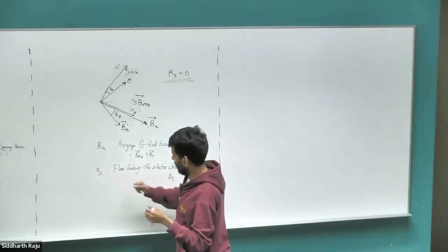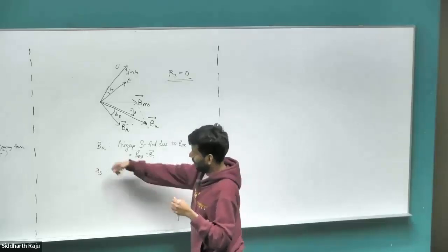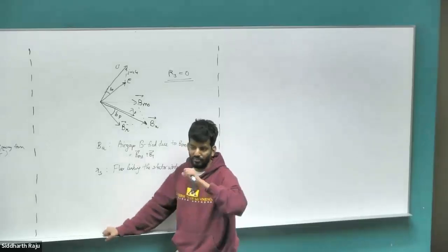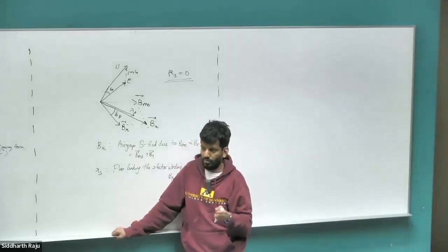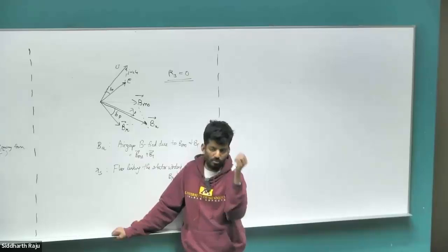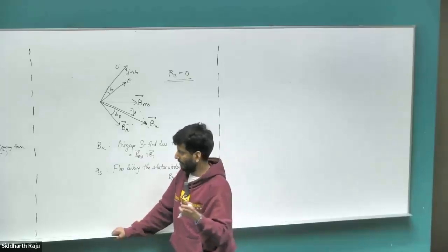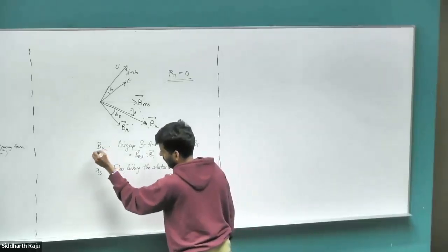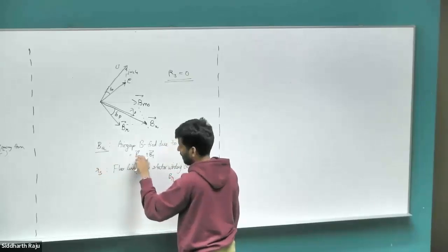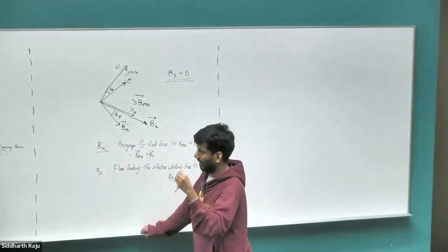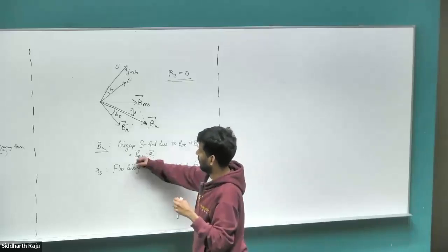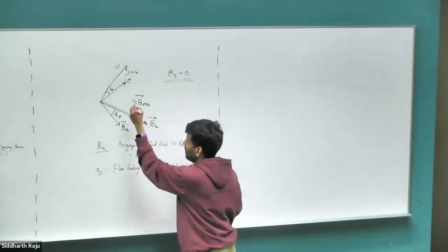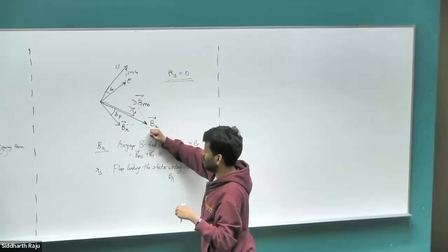So how do we find the flux linking due to both BMS and BR? Basically look at BA, which is the magnetic field in the air gap due to both, and then figure out how this BA couples to the sinusoidally distributed winding of the stator conductor. Then you do this integration over 0 to pi, and you get the total flux linking. Now the value of that would have to be along the same direction as BA, because the only vector entities in that whole arithmetic are BMS and BR. The rest is all just integration, and the conductor density and all of those do not alter this factor. So the space vector for the flux linking the stator conductors would be along the same direction as the net magnetic field in the air gap.